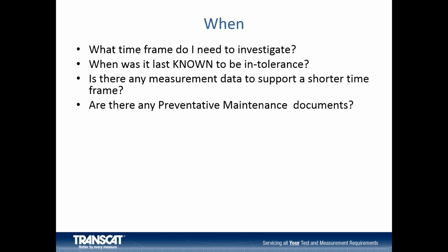One little tip on that, make sure you're looking at the as-found data. Often you might get 2 sets of data. One says as found, one says as left. Make sure you're looking at the right set before you get going.